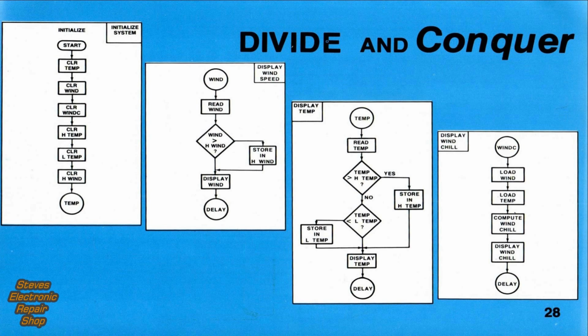The key to an effective program is to attack tiny portions of the overall program. In other words, divide and conquer. Therefore, we can divide the system flowchart into many subroutines. Then we attack each subroutine separately. As individual problems surface, subroutines can be written to cope with them. All of the subroutines will then be combined to form the control program.